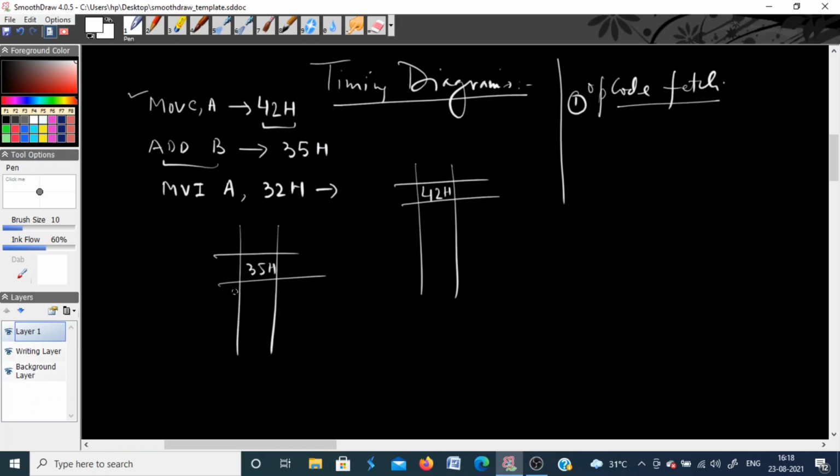So whenever the processor fetches this opcode from the memory, it will decode it. So it will come to know that it has to move the contents of A into C. There is already some data in A that will just be transferred to C. So this instruction is executed using a single opcode. There is no other cycle basically. Opcode fetch is the only machine cycle that you can say.